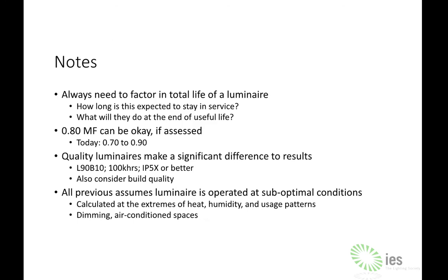Today I've proved that you can get from under 0.7 all the way up to 0.9 in a standard office fit out, purely based on the luminaire that you use, not changing spacing or anything like that, or room conditions. It can be quite variable. It's generally closer towards the 0.7 side of things than the 0.9 side of things. And those quality luminaires do make a significant difference to the results.